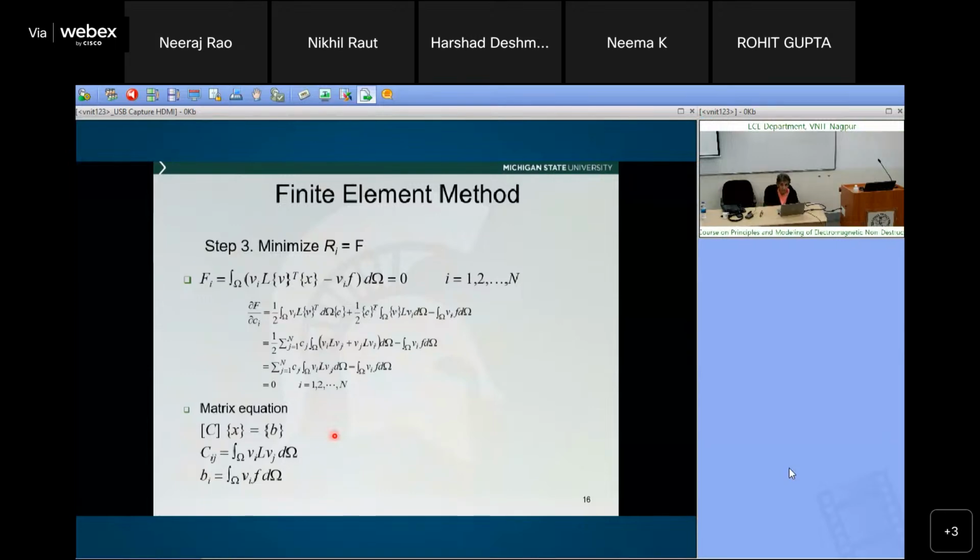But in general, when you're doing the forward problem modeling, even if it's 1 mile or 100 miles, you are only interested in the region where there is a defect. You are only interested in the defect signal, okay? So you can still always truncate it to a smaller region, apply absorbing boundary conditions so that the wave keeps going, and look at it that way. Okay.